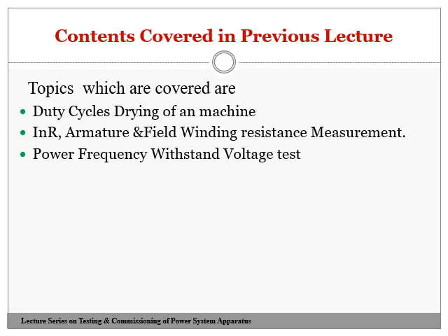During the drying process, the insulation resistance is measured. It is measured with the help of a device, the megger, or any method capable of measuring the insulation resistance in terms of mega ohms. Since the insulation resistance will be in mega ohms, any method available for measuring insulation resistance in mega ohms can be used.